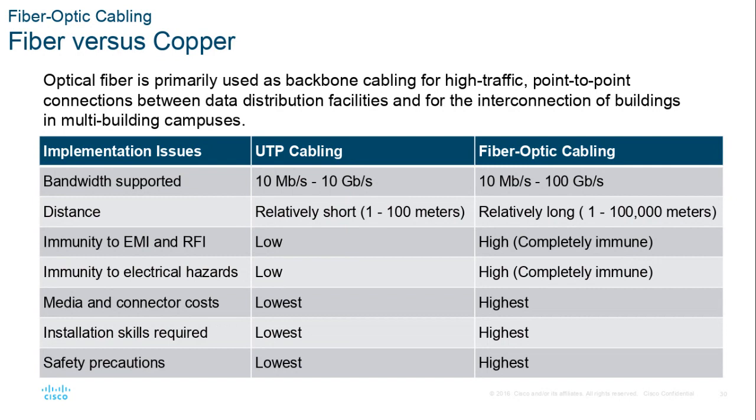What's the rule that the laser guys use? Do not look into a lit up fiber optic cable with your one remaining good eye. Well, yeah, it can blind you. So, you know, they use tricks like shining it on an index card or looking at it with the camera on your cell phone. Don't look at it with your eye. It can actually cause blindness.